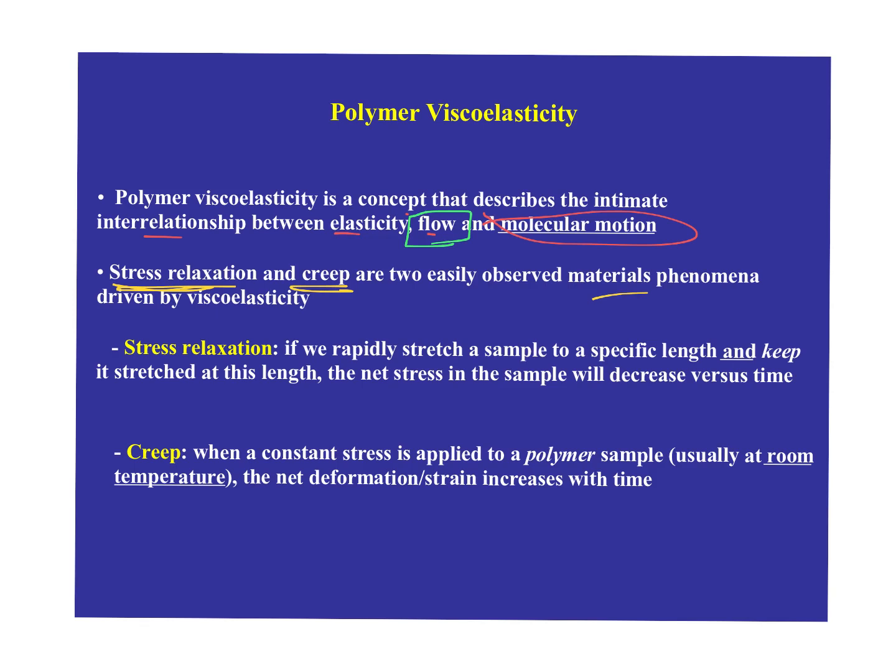And the example I already gave you guys was about the biomedical acetabular cups. In the early days, before they knew how important molecular weight and cross-linking were, they had issues where the cobalt chrome head was creeping into the acetabular cup. Basically the polyethylene was being tunneled into by the cobalt chrome head. That was because they didn't really appreciate the fact that at 37 degrees, polyethylene creeps. Unless you crank up its molecular weight and cross-link it, it's going to creep.